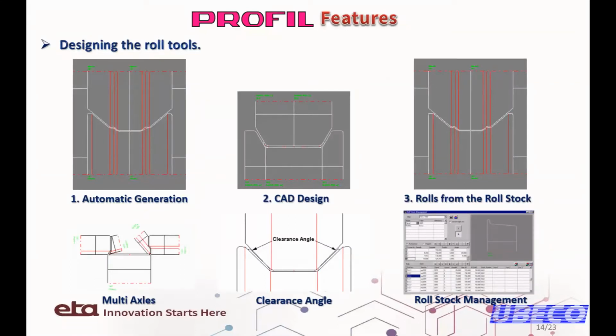Profil provides different approaches of generating roll tools. You can automatically generate roll tools by selecting the top and bottom line segments, or you can import the roll tool created by CAD software.